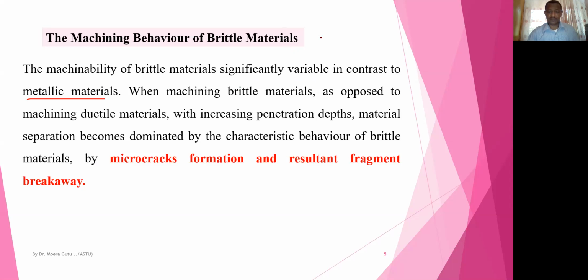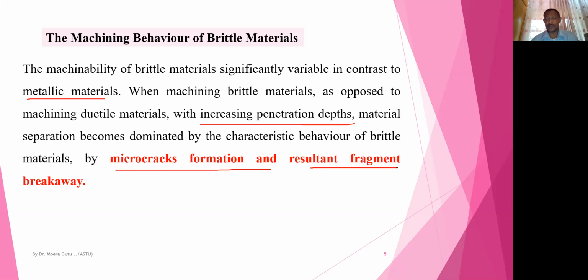When machining brittle materials as opposed to ductile materials, with increasing penetration depth, the material separation becomes dominated by the characteristic behavior of the brittle material. So there is a formation of microcracks and the resultant fragment breakaway of the material. This has its own problem because the cutting tool can crack also. It is difficult to get the required smooth surface finish on the machined surface. So these are the behaviors of these hard materials.